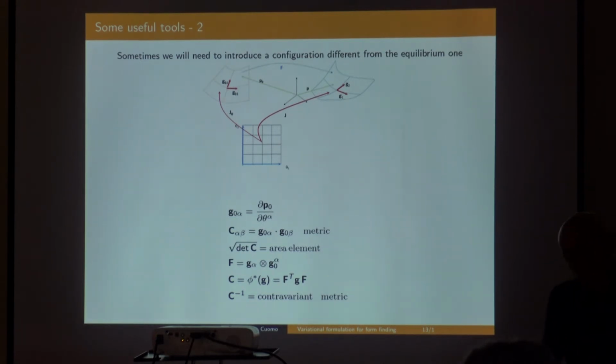For instance, typically, how we proceed: I will not show now how we do the form-finding procedure, but we start with a drawing in Rhino. In the drawing we reproduce the topology of the membrane. So there are some fixed edges, for instance, and then the edges are joined by any line. This will be the original arbitrary configuration where everything is known.